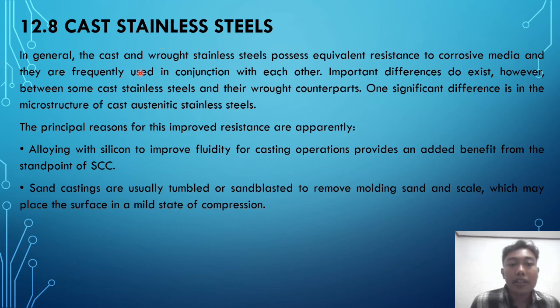Next, 12.8 Cast Stainless Steels. In general, cast and wrought stainless steels possess an equivalent resistance to corrosive media, and they are frequently used in conjunction with each other.